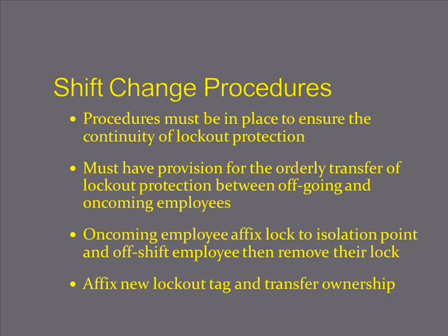Your energy isolation device must only be removed by you, who is the authorized employee who installed it. The company lockout-tagout program includes specific procedures for emergency lock removal when an authorized employee is not on site or left the company, an authorized employee lost their lockout-tagout key, or an authorized employee that installed the lockout-tagout cannot be identified.